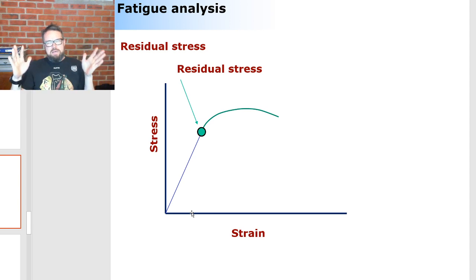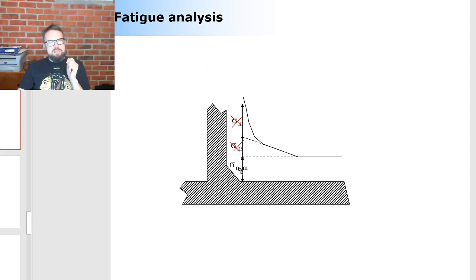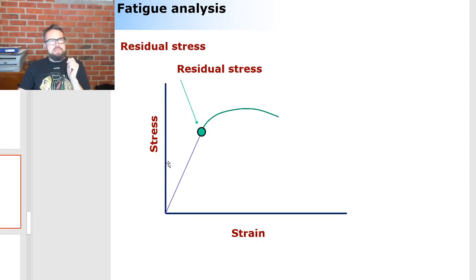but instead you will have some permanent deformation. This is how the structure behaves at a large scale. At the microscopic scale, when you look at the weld toe, this particular detail here, it is fair to say that the residual stresses due to the welding process are pretty much at the point where the linear phase ends and the nonlinear phase starts. This is when permanent deformation takes place. This is good to keep in mind, because as soon as you start loading, you already step into the nonlinear phase, meaning you're introducing, very locally, permanent deformation to your structure. That is crack propagation.